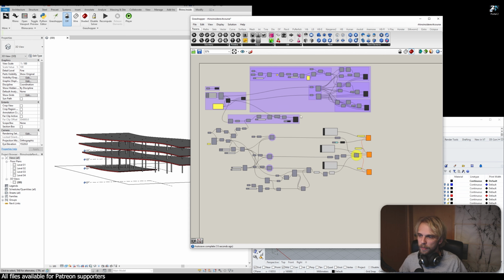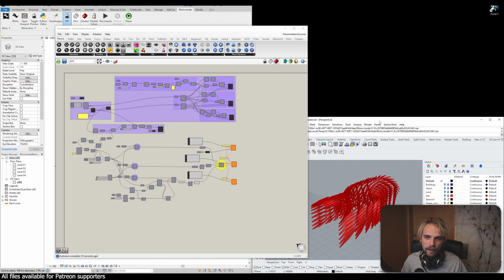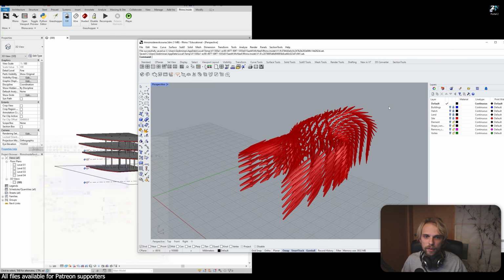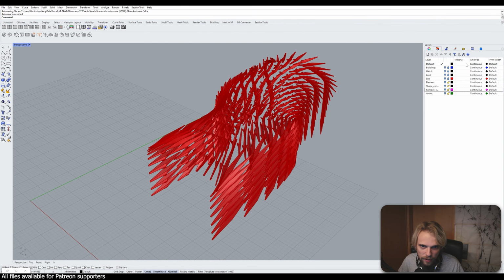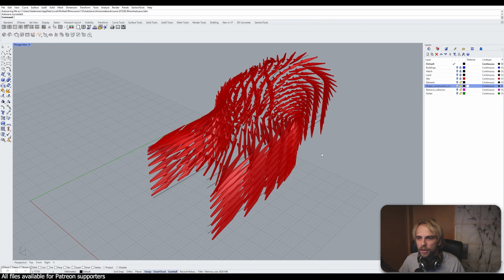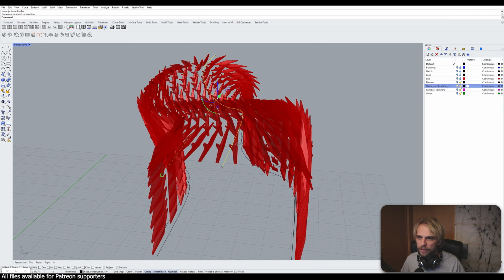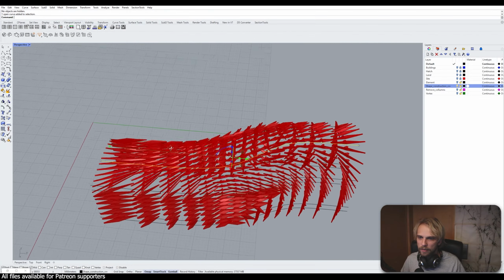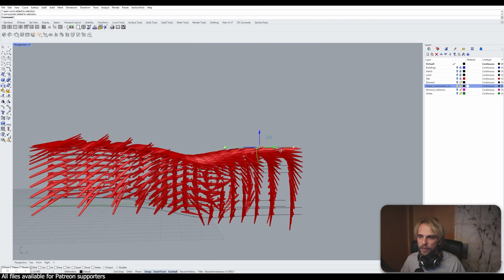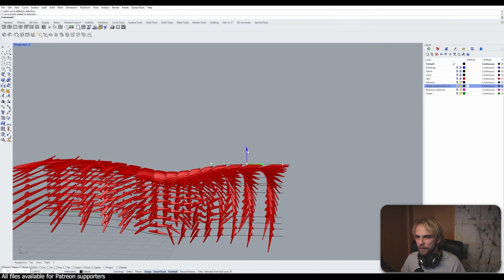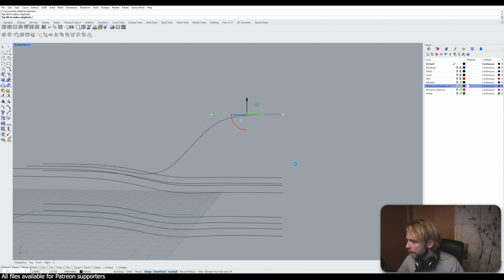This is very good because if we were to change something, let's say I go back and I kind of want to mess things up. Let's go to show selected. Come on, not show selected, sorry. It's going to be under shape, construction curves. And if I were to select, let's say, my curve right here, the center line, and I were to say, okay, these 3 points, I actually want them to be higher, like yay high, right?